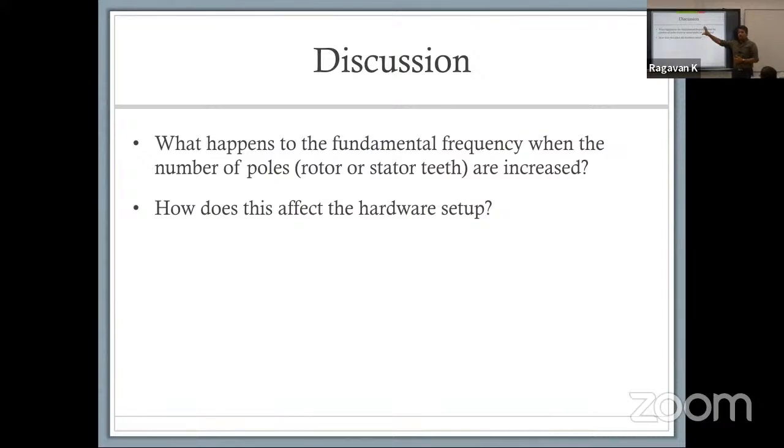But the idea basically is your hardware constraints change there. Next, sensors. Your sensors have to have a response time, right? You need to have the resolution, your throughput has to be good. You might get to a scenario in which you have to have an analog setup so that you don't have any ADC error. You might have to convert them using an analog setup so you can get much faster response time. You might need to end up changing from having individual phase sensors, let's say in voltage, to estimating some of these quantities, because you can use the switching cycle and, let's say, the DC link voltage to identify what your voltage level is going to be.